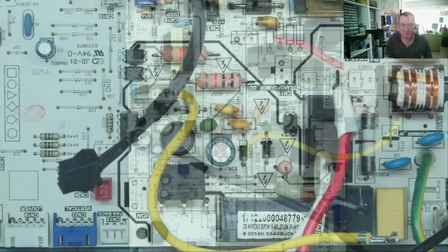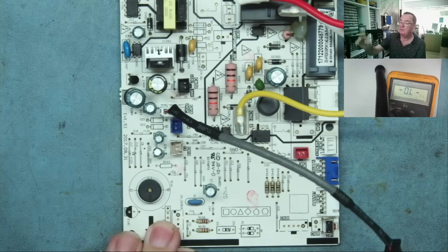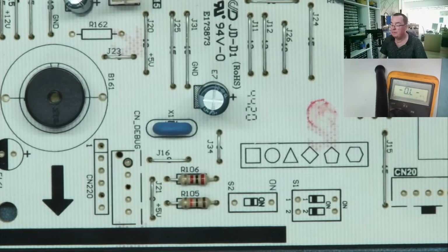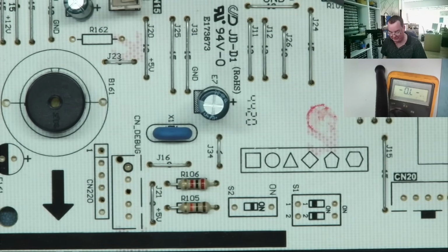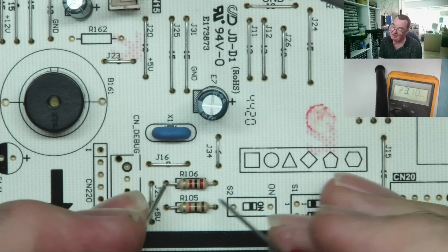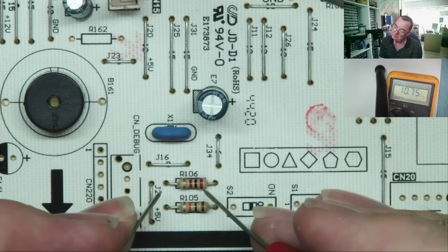Let's get on with it. We should try to do this in a fairly methodical fashion. So let's start with the top side first, okay? Resistors. You can't always test these in circuits. Sometimes they won't read correct anyway. It helps also to learn the colour code, guys. You don't want to keep looking these things up.